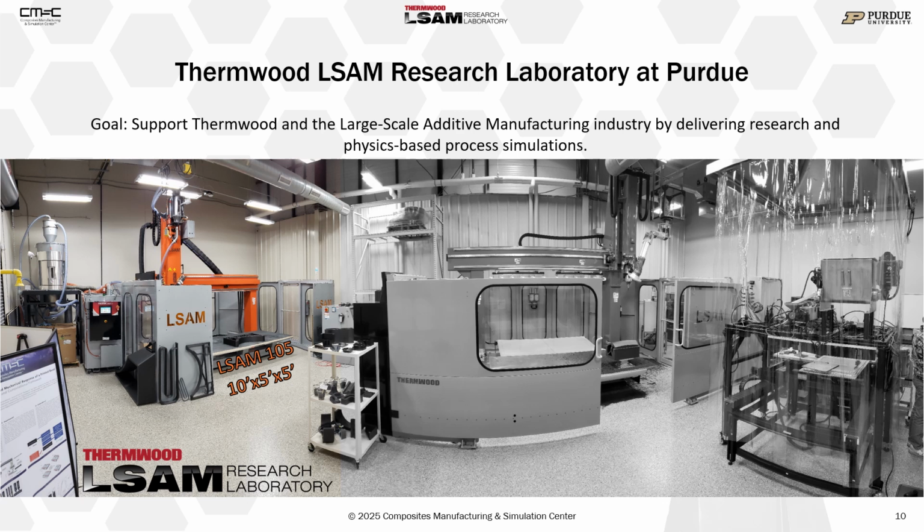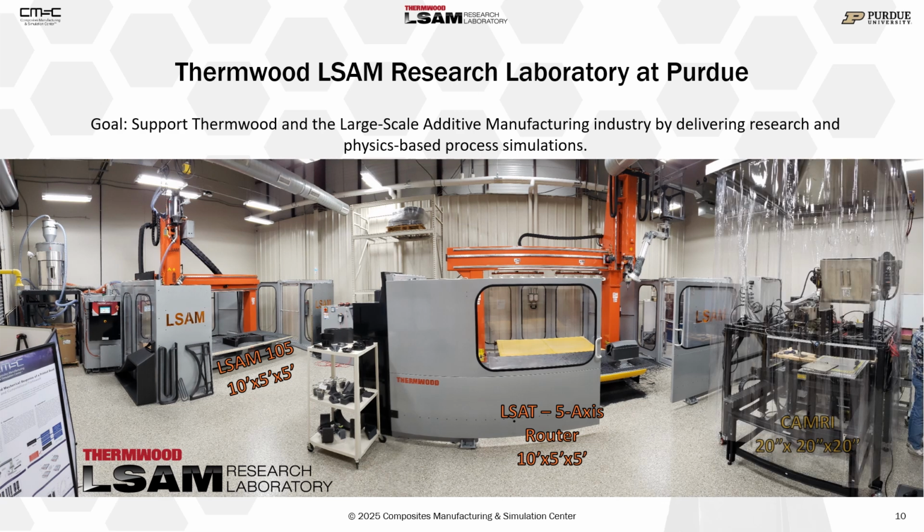Now we have developed a key partnership with Thermwood that has led to the establishment of the Thermwood LSAM Research Laboratory with the goal of enhancing the confidence and supporting the large-scale additive manufacturing industry. The LSAM laboratory features an LSAM 10.5, which has a build envelope of 10 by 5 by 5 feet, is equipped with a 40 millimeter melt core, and can print at rates of nearly 250 pounds an hour.